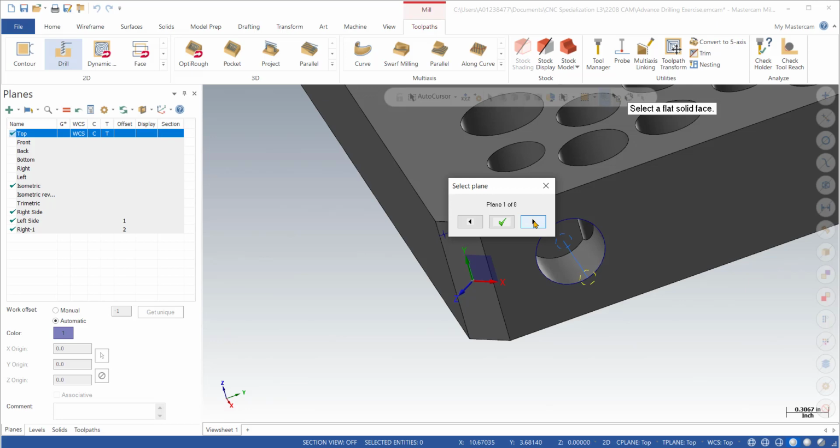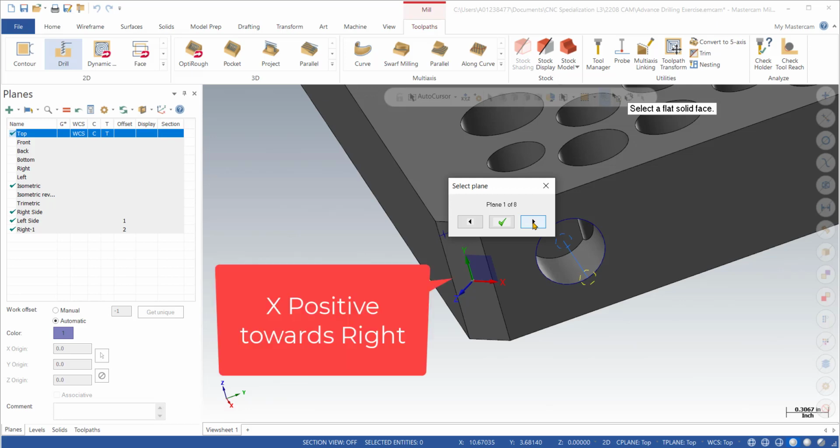So if this plate, I'm holding it in the vice, and the vice is clamped in a way we generally do on the machine, like handle towards the operator, then probably this is the right choice because our X positive will be towards the left, and Y positive will be away from the operator, and Z positive looking upward. So that looks like the more practical way. So yeah, I will just pick that, say okay.